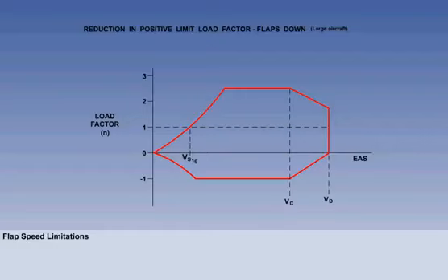We know that flaps are designed to reduce the takeoff and landing distance, and are only used when the indicated airspeed is relatively low. To keep structural weight to an absolute minimum, the flaps themselves, their operating system and attachment points, are not built to withstand the loads that would be applied at higher airspeeds. In addition, with flaps deployed, the aerodynamic efficiency of the wing is increased, so a gust would subject the wing itself to greater stress.